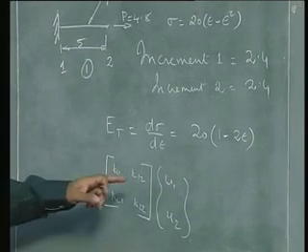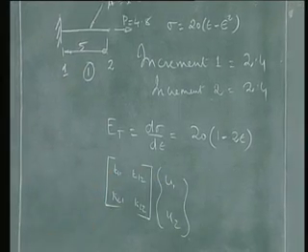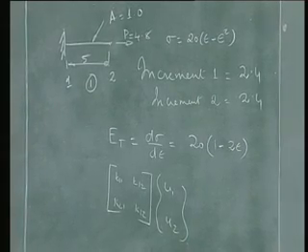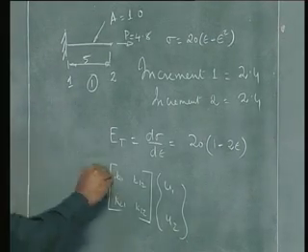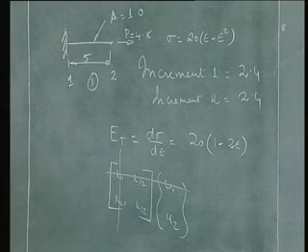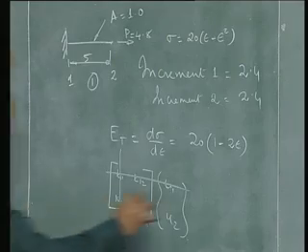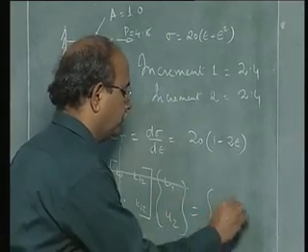I can write down my stiffness matrix, then I can eliminate one of them because u1 is going to be fixed, or u1 is equal to 0. So those two are eliminated. So I have a simple equation of the form K22 u2 is equal to F2. Of course, this is equal to F.